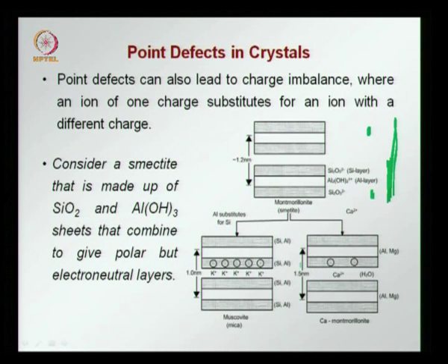You can see here that it is 1.5 nanometers, whereas when potassium cations are there it is only 1 nanometer. So, the space between the two sheets now is bigger. This gives the possibility that water molecules can enter between the sheets, and when water molecules enter between these sheets they lose some of their bonding and start separating, and this gives rise to the expanding behavior of some clays.